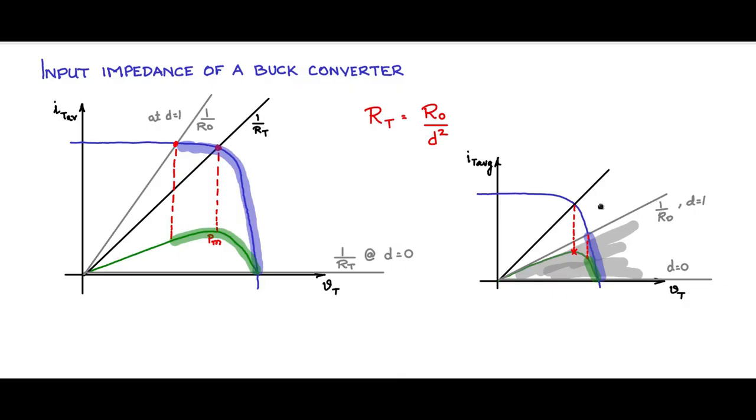So you have to be very careful when you design the converters, whether it be boost, buck or any other converter. The load line analysis has to be done first to ascertain whether that particular converter can really provide maximum power point operation.